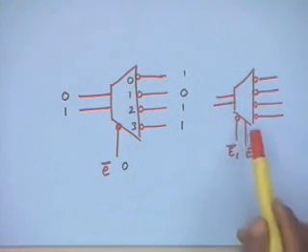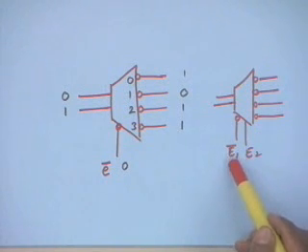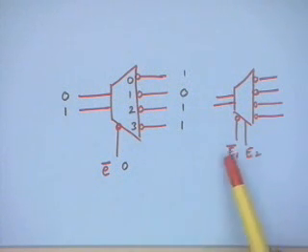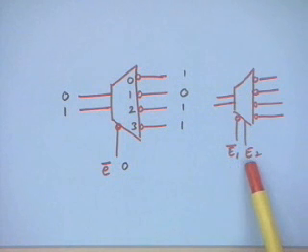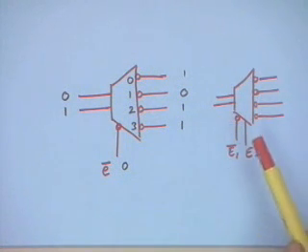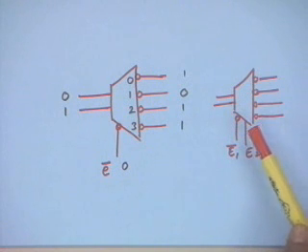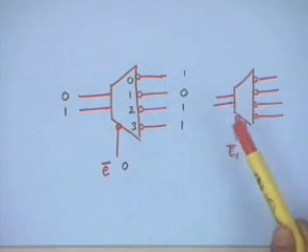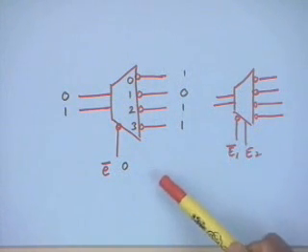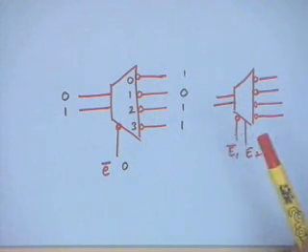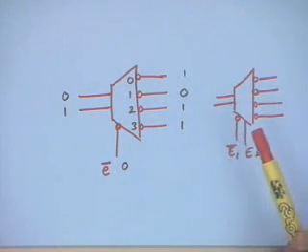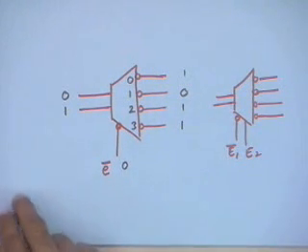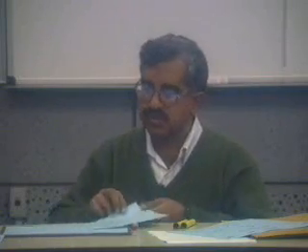So you also have multiple enable decoders. That means here E1 has to be 0 and E2 has to be 1 for this decoder to be enabled. There is a gating inside, and both these enable inputs are to be satisfied, so this has to be made 0, this has to be made 1 for the decoder to be enabled. Of course, a question can be why does one require this? But we will see that there are situations where you want to enable decoders based on multiple conditions. One could gate these conditions outside and then use the decoder, so it's perfectly fine, you need to have only one enable. But if you provide for gating inside, it helps. The circuit actually also becomes faster rather than doing the gating outside.